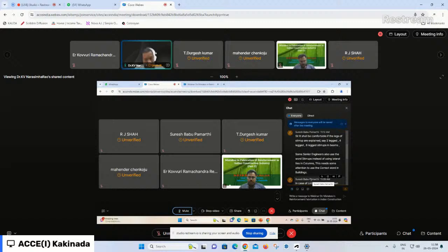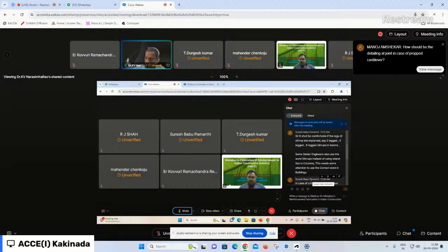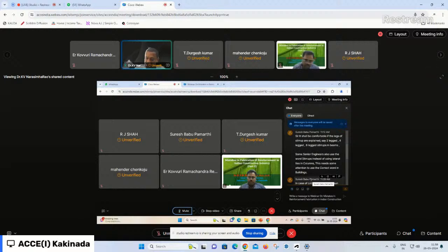The better possibility is available only when the tension steel coming from the sunshade to the lintel beam is a wrap around, similar to a stirrup, when compared to a sigma type of arrangement.